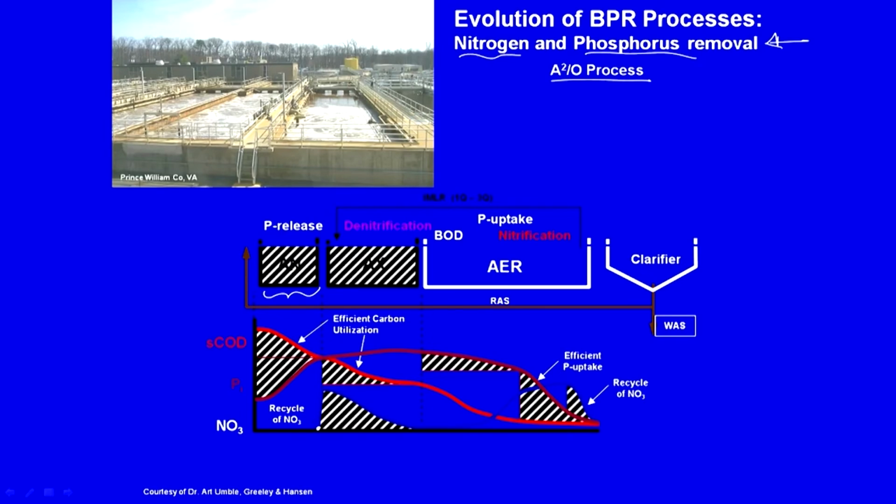And what is happening to nitrates? This is increasing right here. Why is this? Because there is a recycle coming in. So, nitrates are increasing and then denitrification is taking place. So, nitrates are transforming into N2 during denitrification, and then they are increasing because NH4 plus is going to be oxidized to NO3 minus. So, they are increasing and then recycle is occurring here. So, that is how we are more or less getting nitrogen and phosphorus removal here. So, total nitrogen is 8 and total phosphorus is 1. So, we are getting more or less 8 and 1, with both nitrogen and phosphorus removal, let us see.